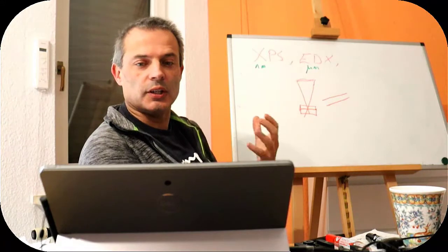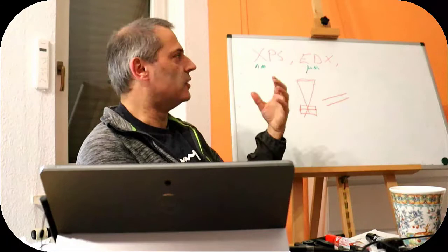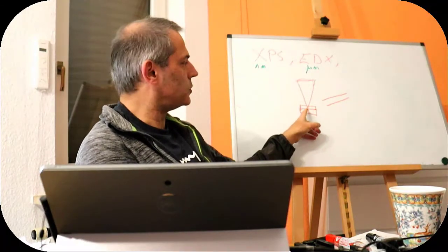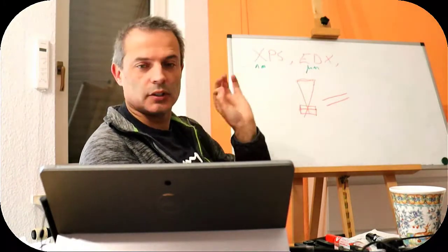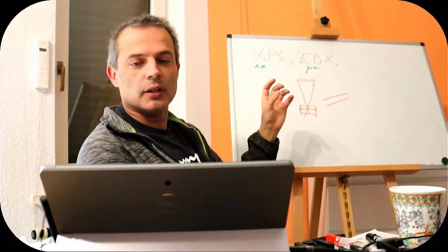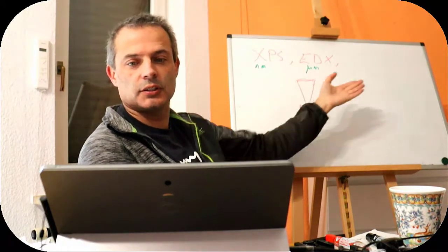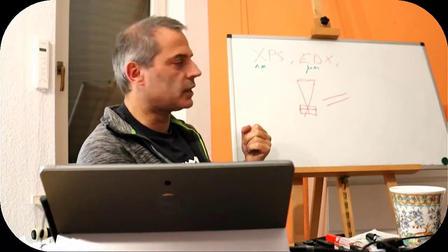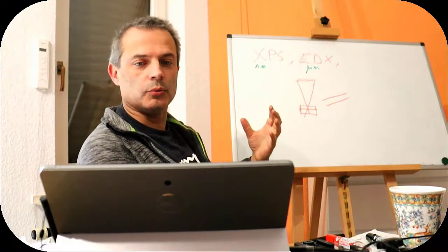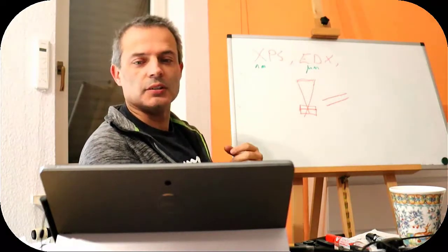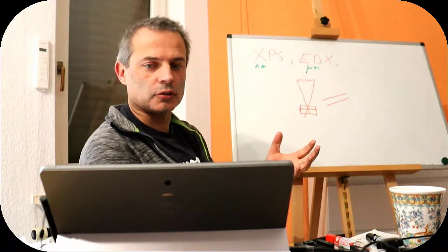For the X-rays, it's really handy because we get an image, although the image is less good than the electron image, because if you imagine we move the point up to the surface and we can get a reasonably good image with a tiny focal point. But if we look at the X-rays, we're looking at all of the X-rays down to here, because the X-rays can escape from a greater depth than the electrons can, and so our imaging resolution is way lower with the X-rays. The good thing about it is it's now immune to charging, so we don't need to coat our sample, which is an issue in electron microscopy.